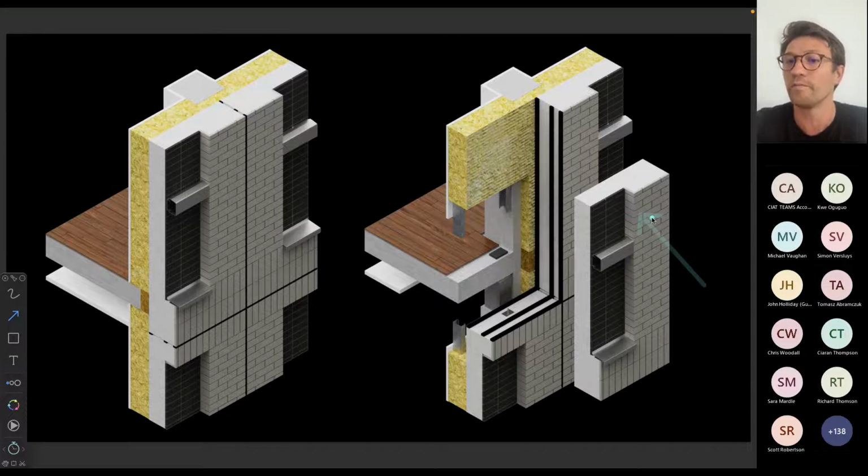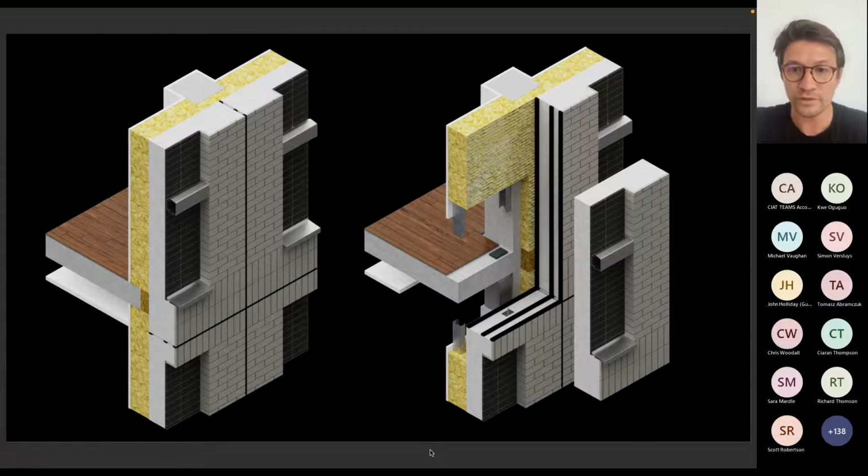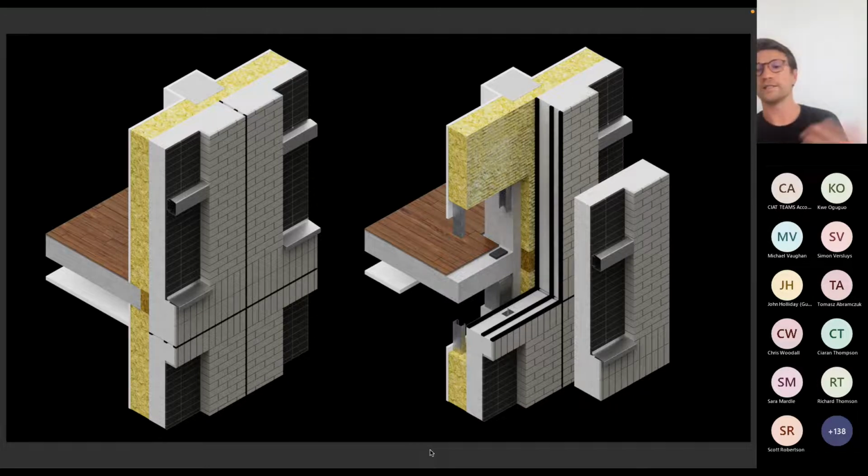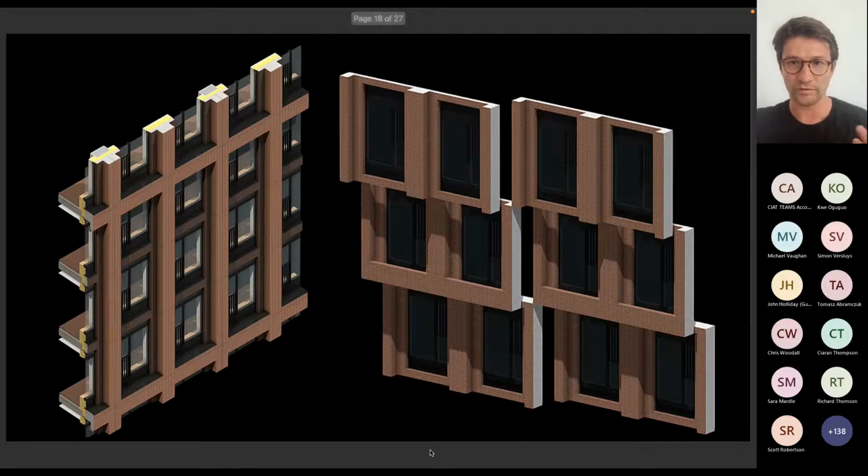It is very forgiving for brick bond. So we can have normal stretcher bond, we can have a vertical stack bond, we can have horizontal stack bond. All of that does not matter and doesn't have any effect on the performance of the precast concrete facade. It's just a veneer wrapped around the precast concrete panel. So it's probably the most forgiving way of achieving a brick outlook with a complex pattern, because you can arrange these brick slips in circles and that will be fine.